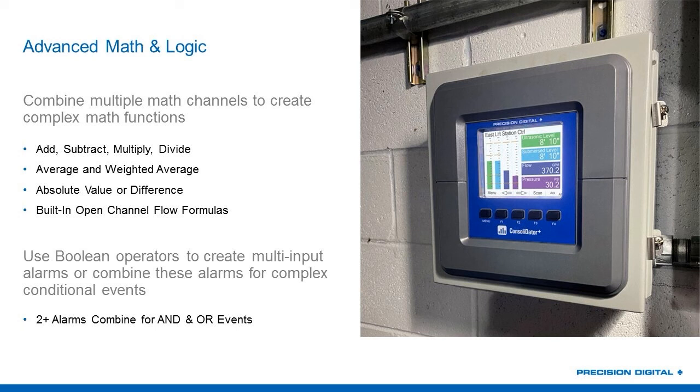However, instead of just averaging both, I made it so that 80% of the average was coming from the trusted level sensor, and only 20% was coming from the not so trusted level sensor. That's just a very small example of how weighted average could be used.